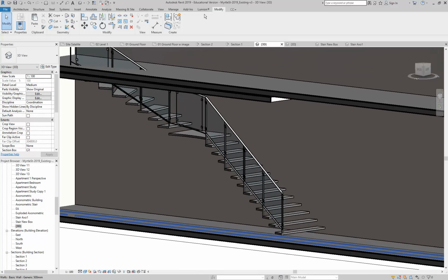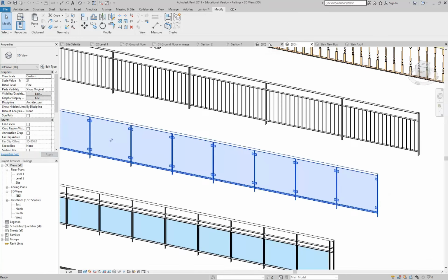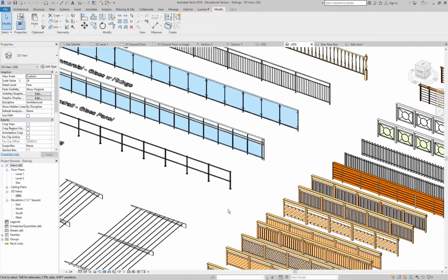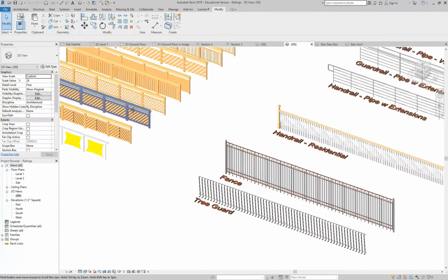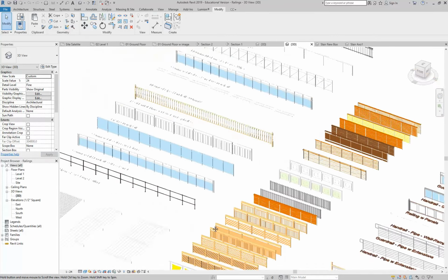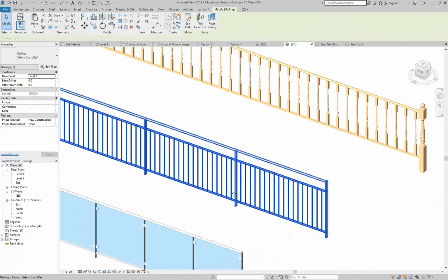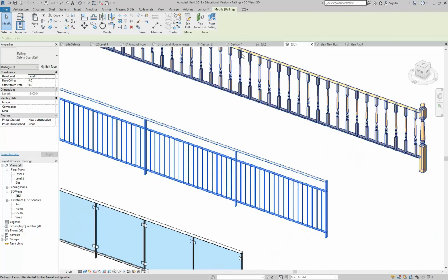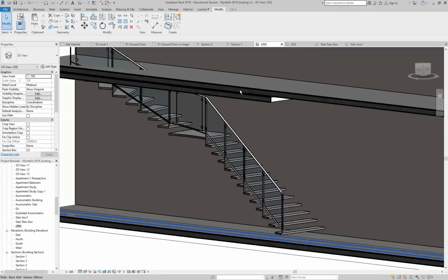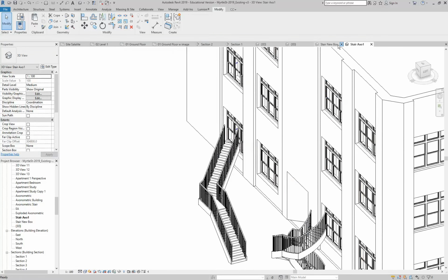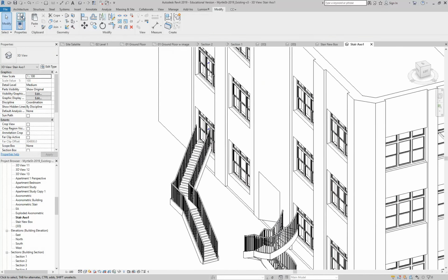Okay, so I'll go back. And this is the nice thing about the tabs in the new version of Revit. You can switch back between files pretty easily and just try a different one. So let's try this one. Yep, copy to Clipboard, back to my other file, and I'll go to the view that shows everything and then paste.